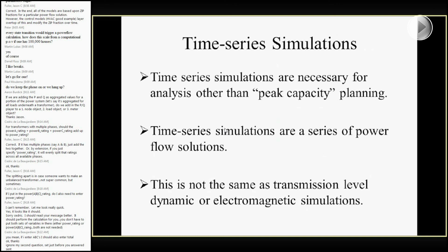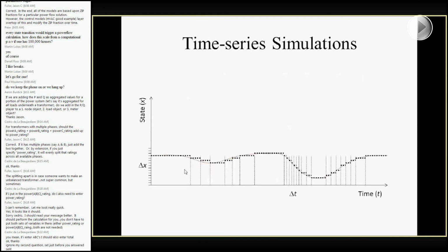It only does down to a second level or higher, depending on what you're looking at for your minimum time step. We are adding in the capability to do these dynamic level simulations, but it's not explicitly part of the Powerflow module itself. It's kind of an over-encompassing capability we're adding right now, but it's going to be part of the 2.3 and 3.0 build, so it's not even in the one that's included with this course material. But just something to be aware of if you're looking at simulations that might need that capacity.